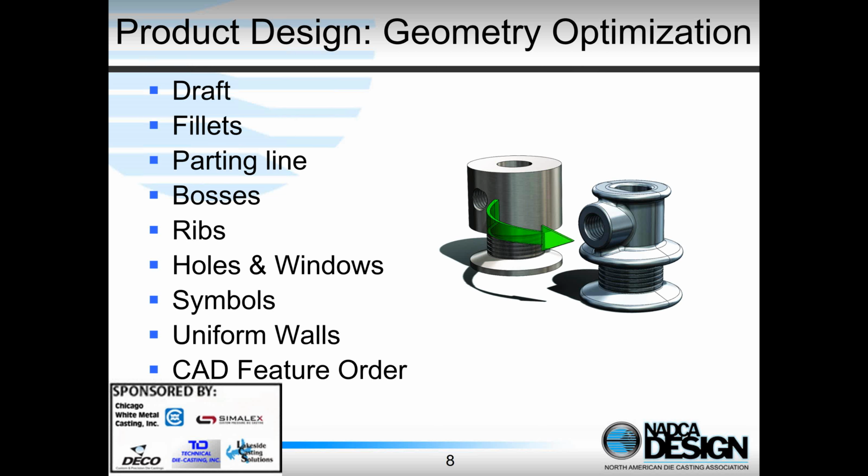Casting is absolutely a fantastic process, but certainly we're going to generate more porosity and more defects when we have a large variation in wall thickness. And this is not just true for die casting, it's true for all types of casting processes. It's based on how the metal solidifies, and most casting processes are going to struggle with large variations in wall thicknesses over big areas of the cast.